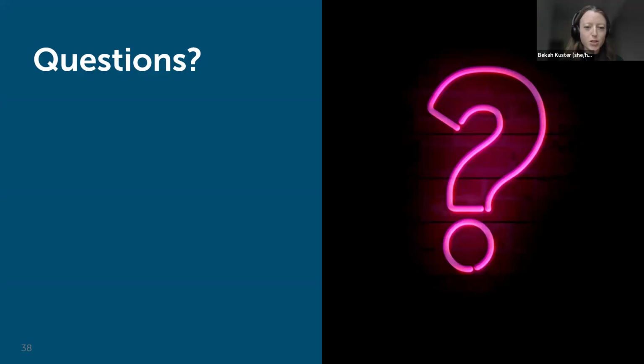Great. Okay, one more, and then we'll maybe answer some in the chat. Heather asks, is there a better or worse location for the outdoor unit of an air-to-air heat pump? Do they do better on the south side, where they may benefit from a bit of solar gain to surrounding air temperatures? It's a good question, and a little situation dependent. On a simple level, hiding them in the shadow on the north side of your house means they're in colder air, so they run at lower efficiency more of the time.